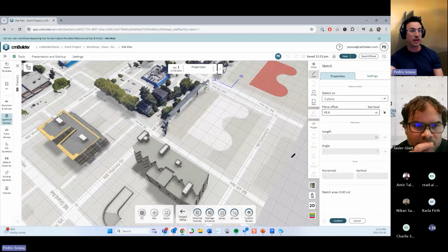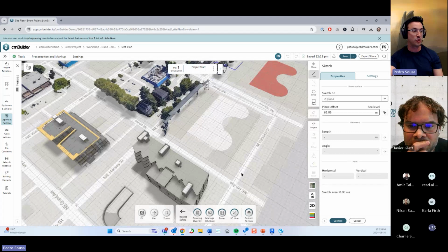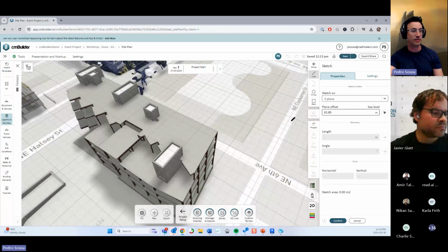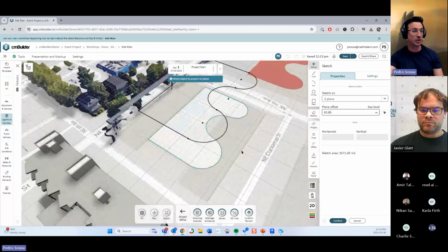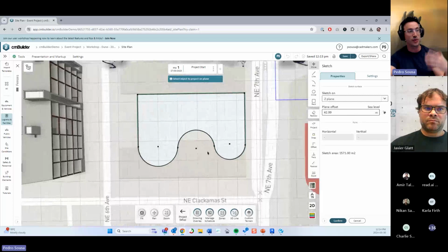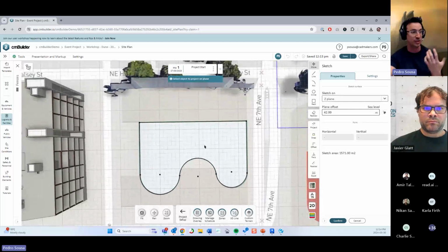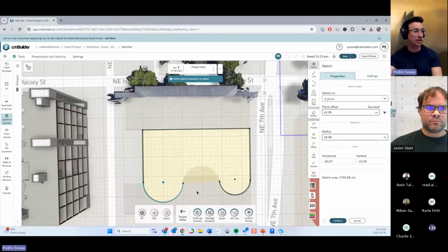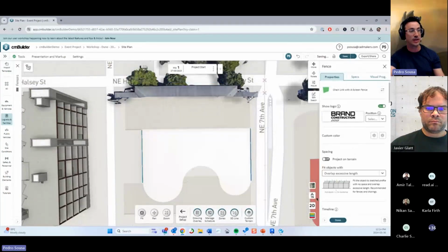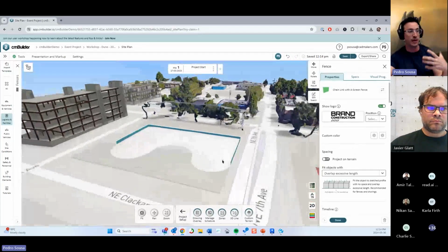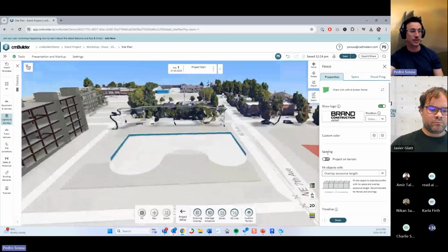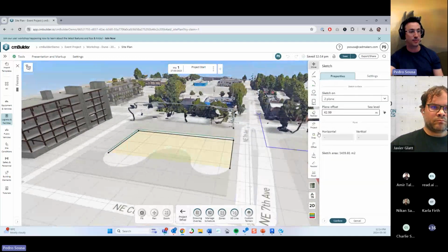But keep in mind that you can also use the projection tool combined with other things. So for example, if I want to project the shape of this zone over here, but I want to edit it, I start the projection of the zone, and I'm actually going to use just these parts over here, right? So you can steal just a part of your zone sketch, basically. Cool. So these are the options that we have for that projection.